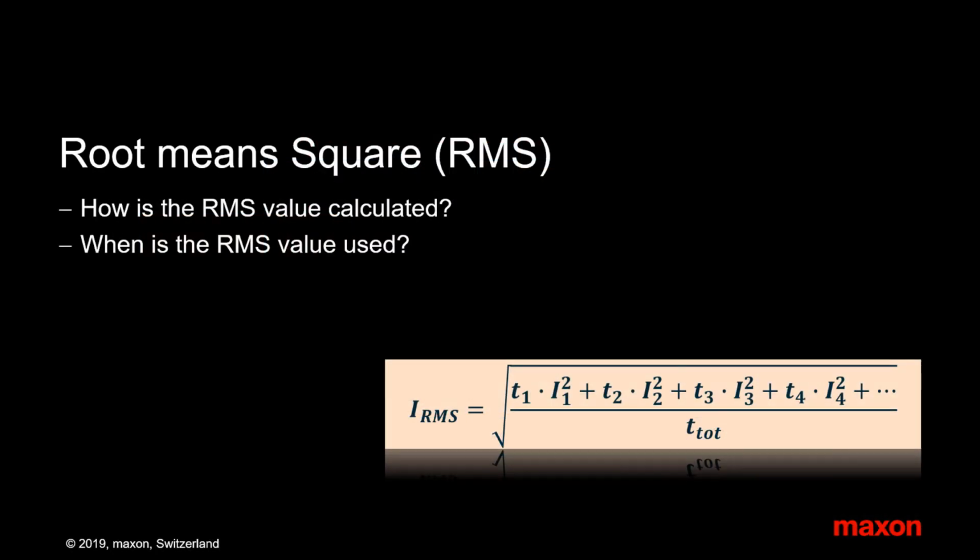That's it. You should know now that the RMS load value gives the average thermal load for operation cycles, and that the calculation goes just as the name indicates. Take the root of the mean value of the time-weighted square load.